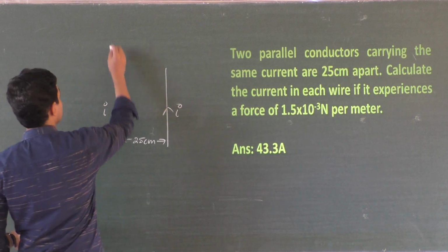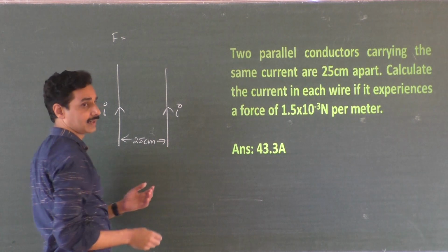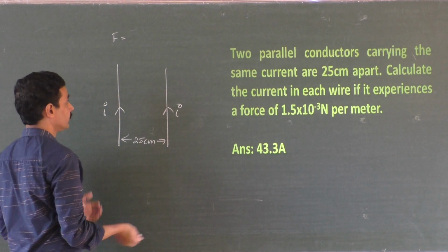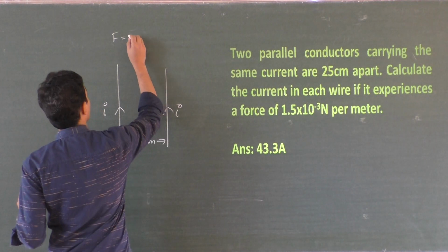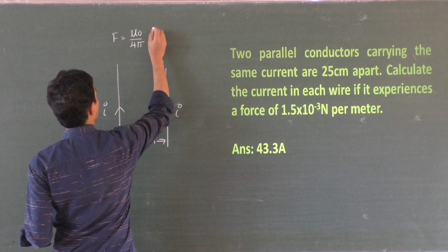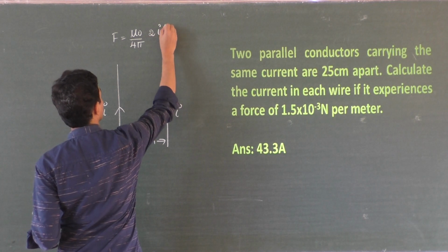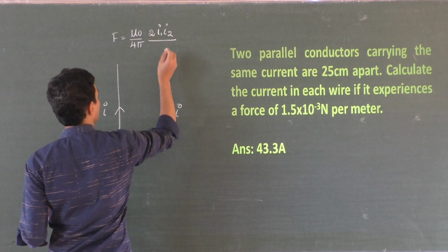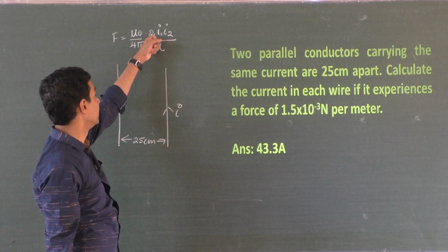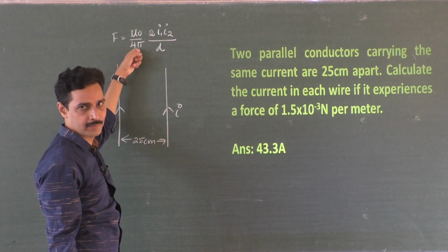You know, the force per unit length acting between two straight parallel conductors carrying current in the same direction. Of course, opposite direction also. Only the force will be different in direction. µ0 by 4 pi, 2 I1 I2 by D, right? IA IB by D. So I should remember here too, because finally you get, see, µ0 by 4 pi is 10 to the power minus 7.